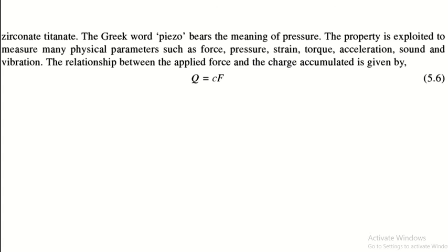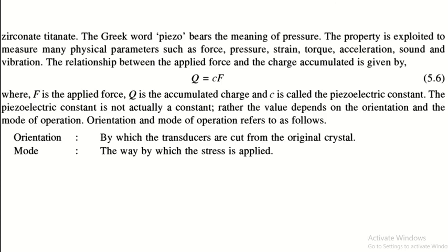The relationship between the applied force and the charge accumulated is given by Q equals C f, where f is the applied force, Q is the accumulated charge, and C is called the piezoelectric constant.